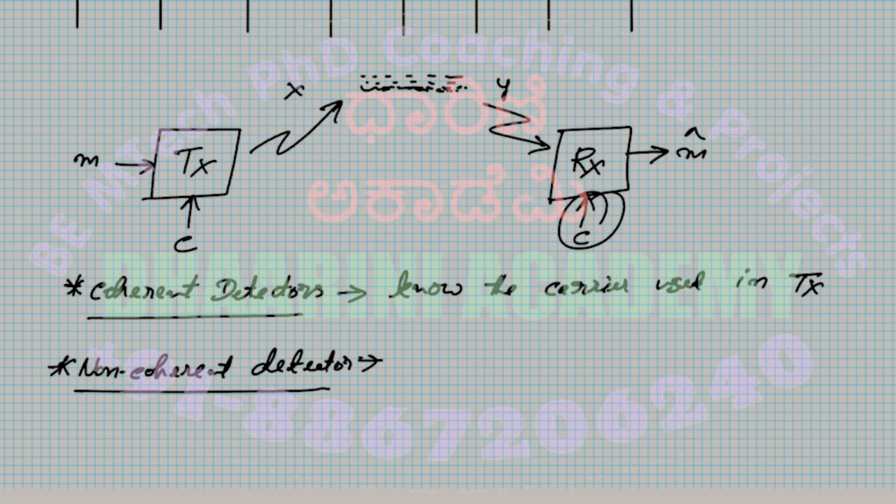When it comes to the circuit, you need to build a completely separate circuit, a part responsible for identifying what C might have been used. Again, that is not perfect. Whatever you guess is not necessarily correct. I might guess that when I look at this Y, the carrier might be 250 kilohertz, but maybe it's true, maybe it's not. So these are complex or complicated versions of the detectors or demodulators.